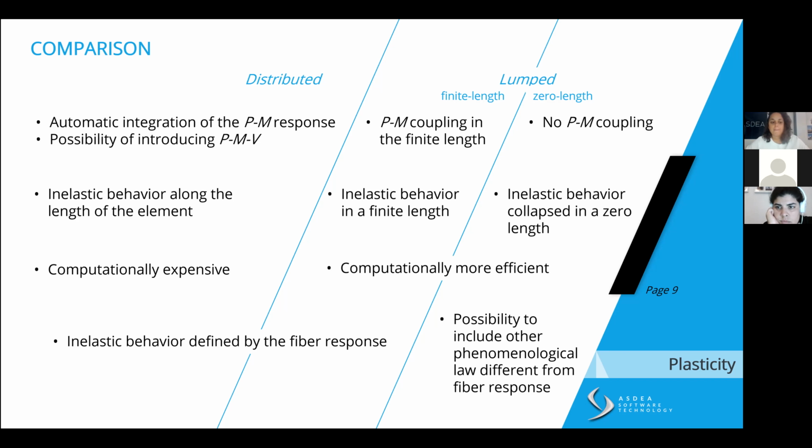But then it's quite heavy to calibrate the way, for example, a hysteretic or a pinching curve works if you want to include, I don't know, bar slip or buckling or any other effects that you have experienced in your experiment. And so if you have a specific curve that you just want to linearize and reproduce and apply to a spring, it's quite immediate to include it into a zero length and apply it as a lumped plasticity approach.